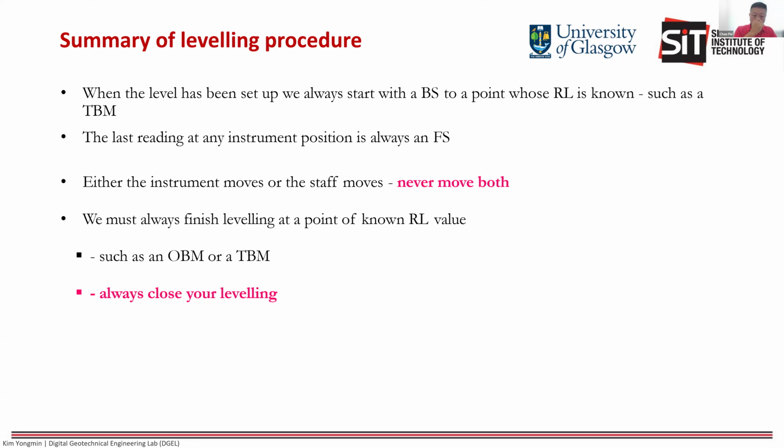Okay, and the last principle: you always need to finish the leveling on a known point, another benchmark in this case, to close your leveling. Why? Because you need to check whether you have any error or not.